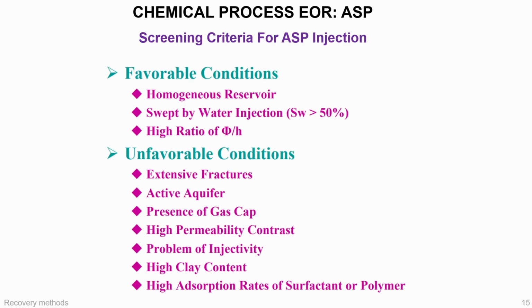This slide continues the ASP screening discussion. In practice, engineers need laboratory core flood tests, fluid property measurements, and often simulation studies before field implementation. Because multiple chemical mechanisms interact simultaneously, uncertainty can be significant. This is another reminder that EOR is not only about concept, but about careful technical evaluation.